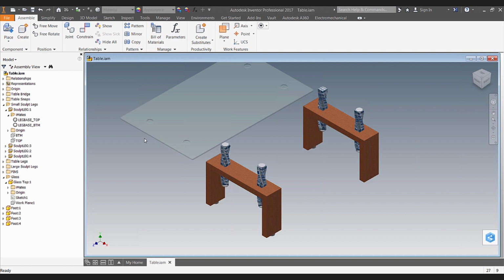All right, sounds good. And then Andrew Johnson asked, do iFeatures yet have the ability to create iMates in parts? So, no. There are ways you can build these, and that's something we didn't really show, but you can take any of these parts with iMates, place them in libraries to become library components. You can certainly use iFeatures to create the holes and things and have iMates on those, but there's no interaction between the iFeature and the iMate.